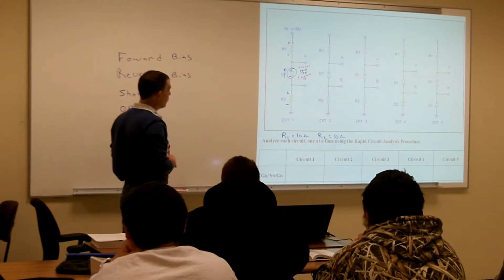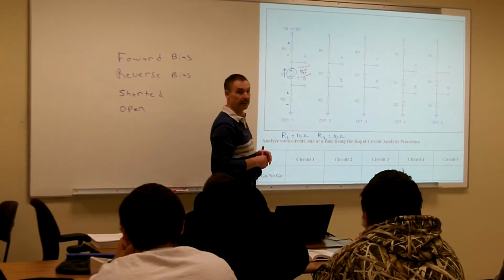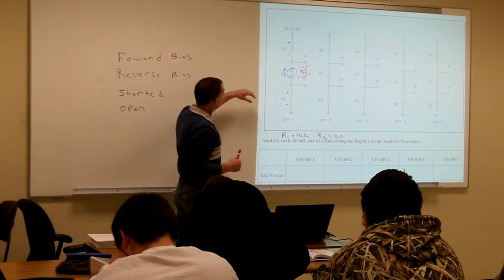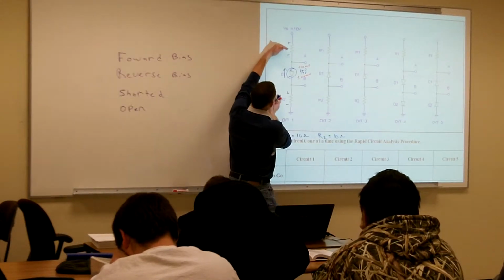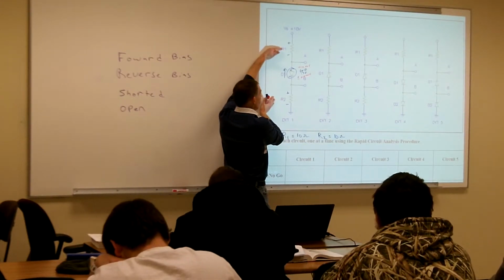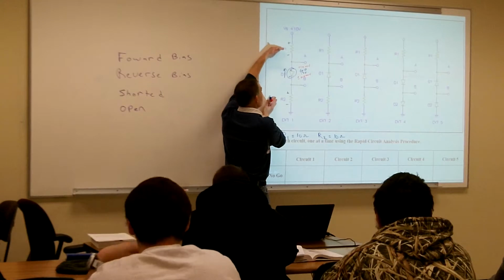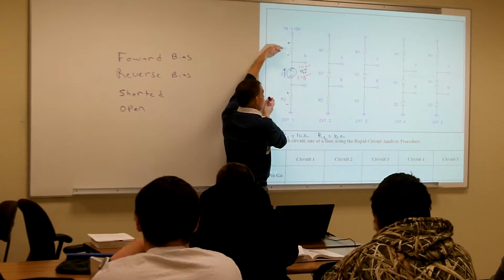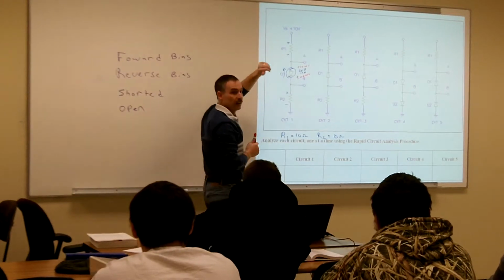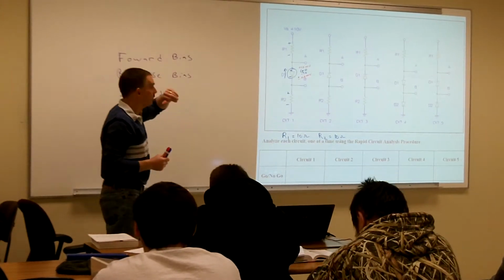Yes, we can figure out RT, but I don't really need to do that at this point. We need to find the voltages going across R1 and R2. So what is the voltage going to be across R1 and R2? If they're both equal in resistance, it's going to be half of the 9.3 volts.